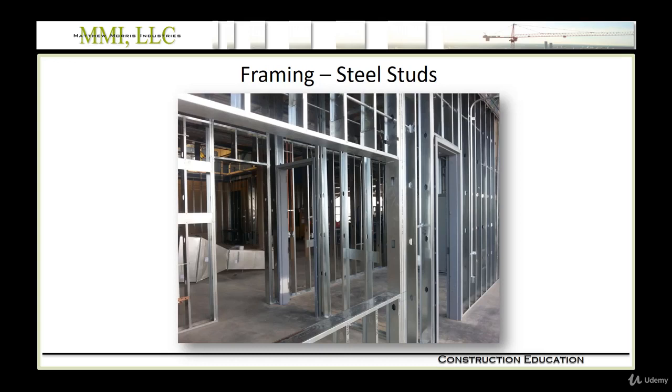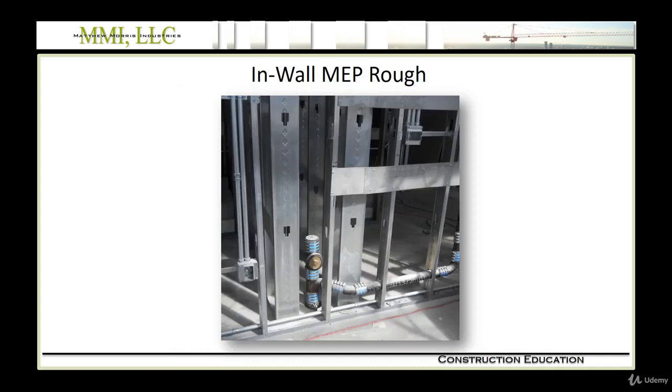And you can also see throughout we have holes punched already in the steel studs and the electrician starting to run conduit. And that would be the next step. After we have framing in place, then the MEP system starts stuffing into the walls. So let's talk about that next, MEP rough-in. So now the framer is continuing elsewhere in the building. Their walls are in place, waiting for the MEP systems to go inside before drywall is hung.